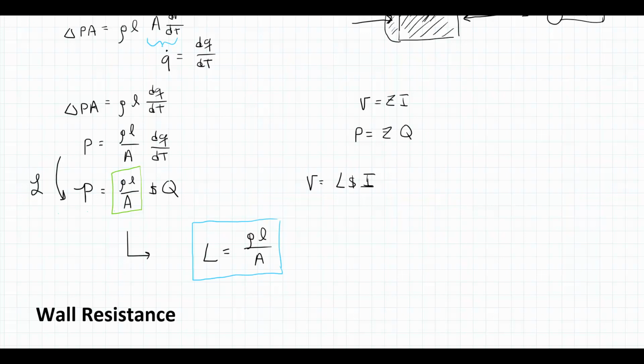But in small systems where we have a narrow cross-sectional area, now the fluid inertia we probably don't want to ignore, and we're going to put the inertia of the fluid itself into our model. So the pipe, which again is analogous to the wires in the electrical system, for narrow or small diameter pipes will not act as just a wire. It will also have some inertia in it that we are going to be compensating for.